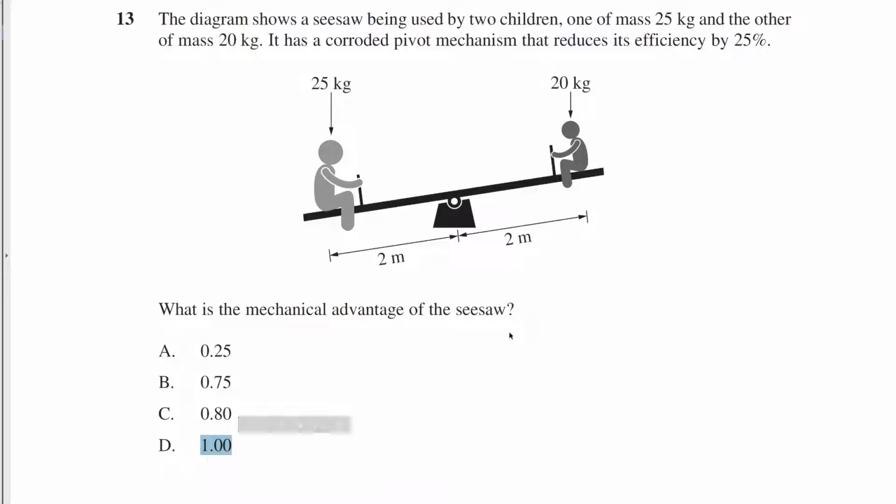Right, so a first order lever can have a mechanical advantage equal to 1, less than 1, or greater than 1. Second order levers, like wheelbarrows, have to give a mechanical advantage greater than 1. And third order levers, like fishing rods or tweezers, have to give a mechanical advantage less than 1. Now in this case, we have a first order lever which could go either way. But because the distances are the same, we're predicting that the mechanical advantage is 1. We're not actually getting any advantage.